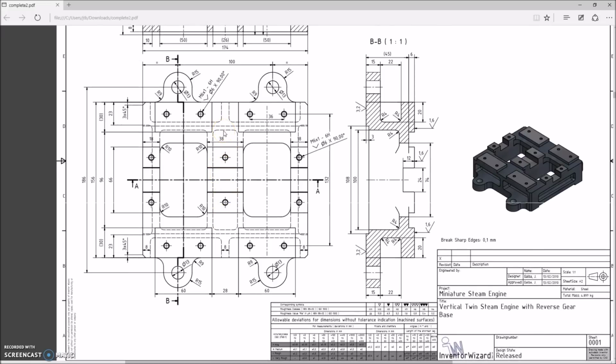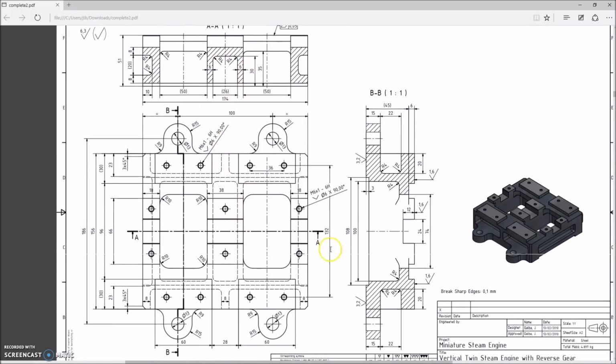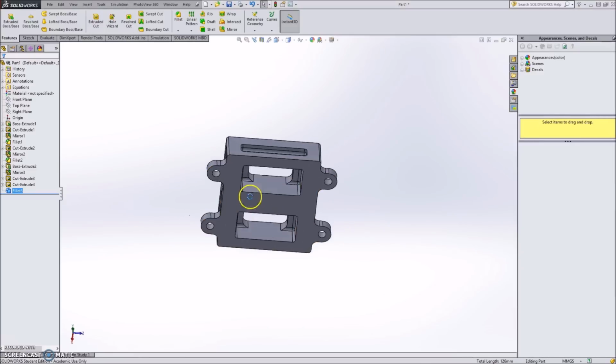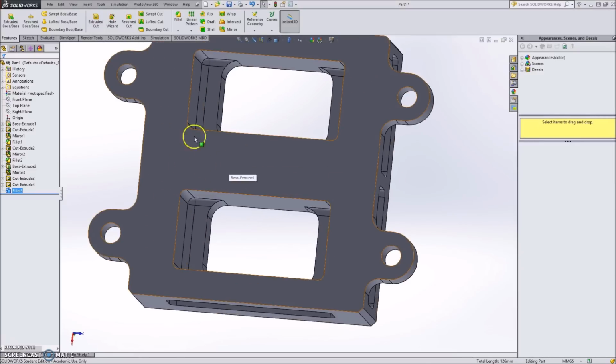And looking over here at this drawing, we may also determine the length of that slot. We see that it is aligned with the two extrusions that we just made, which were 100 millimeters long. So 100 by 26 millimeters and 30 millimeters deep, and that is centered on this centerpiece here.